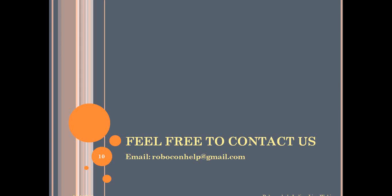So it means that all the PID and PD controls can also be incorporated with Adams? Yes, it's possible, but you have to design your PIDs. Then you can say, okay, I have this much error coming in the model, and I have to integrate in such a fashion, I have to differentiate in such a fashion, and then you can make it like that. There are so many functions available here. With the help of these functions, you can create PID controllers or any other controller you want to do.